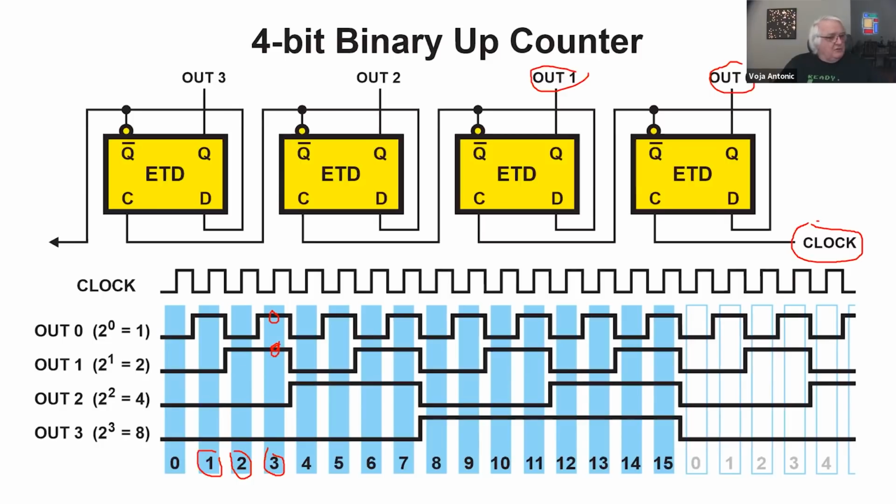I will show you how that counter looks. Look here. This is the 4-bit binary counter. And when I press the button, each time you have a new binary number increased by 1. If you are familiar with binary arithmetic, you can see how it counts. But it can not only count, it has another input which resets the whole circuit. When I press this reset button and press clock, then it resets to 0, 0, 0, 0 always.